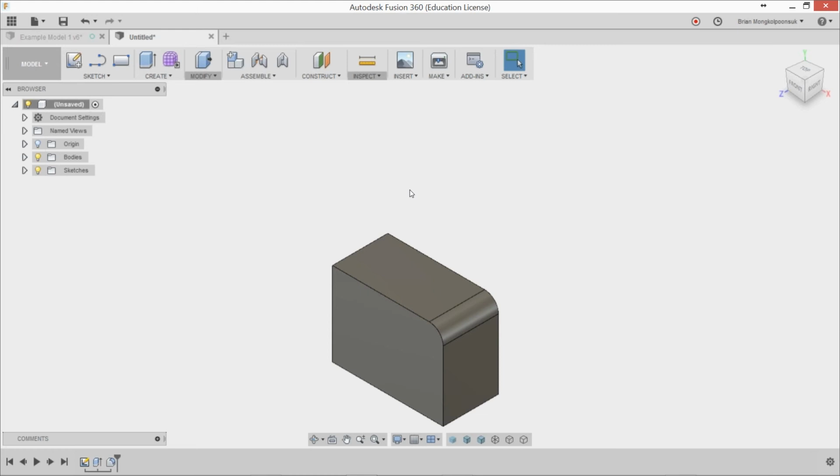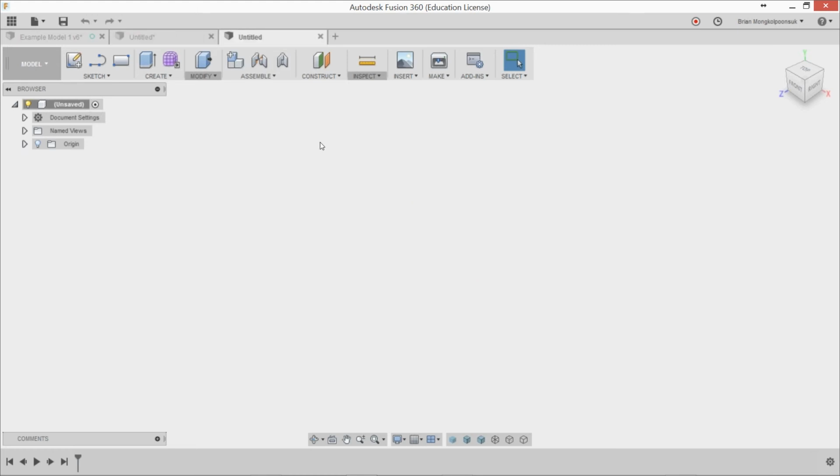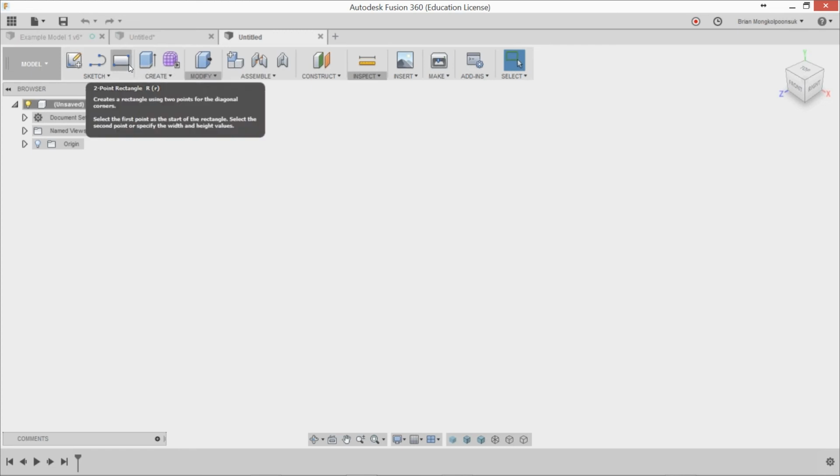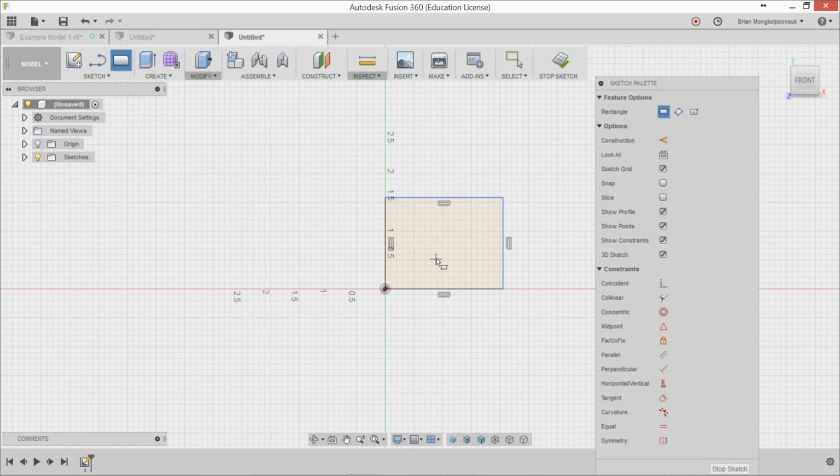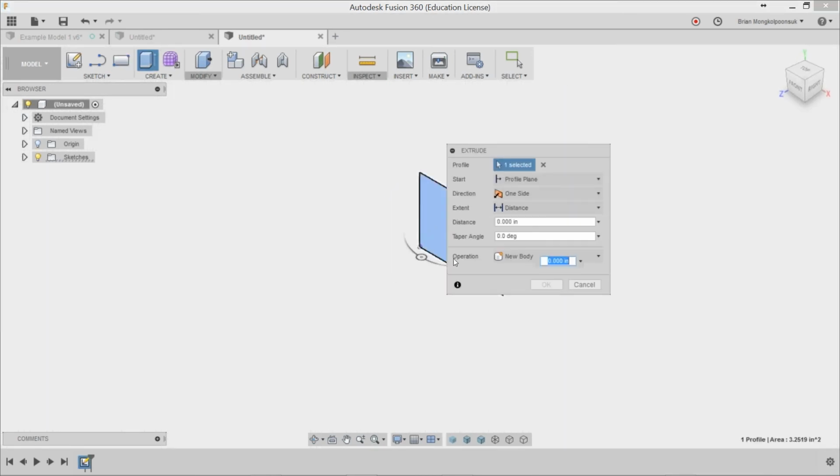So now let's talk about assembly creation. This is a very common topic, and like I said in the beginning, a lot of people ask questions about this. Let me show you the way people traditionally create assemblies in Fusion. This is what we also had a bad habit of doing in the beginning. So normally you would go straight to the sketch, create a 2D sketch, and extrude that out to a 3D body.